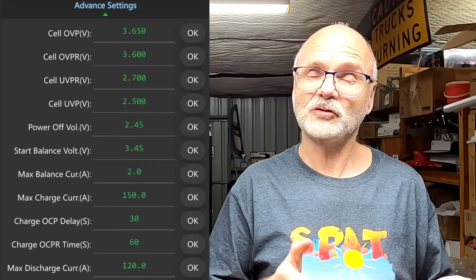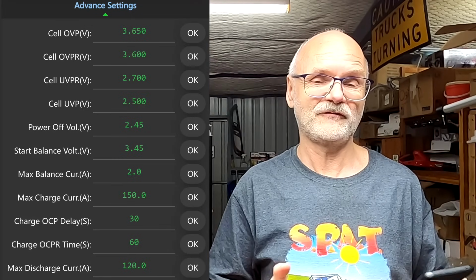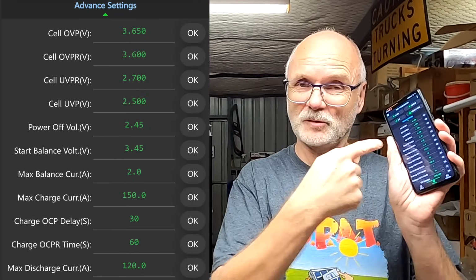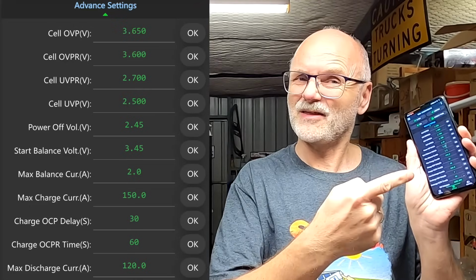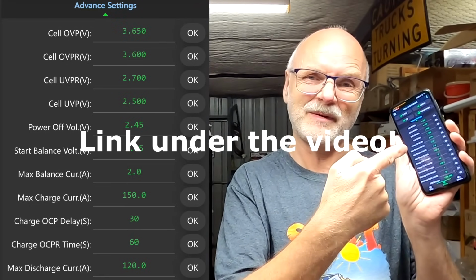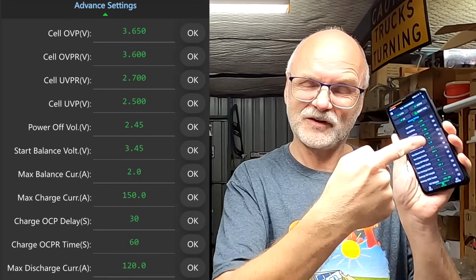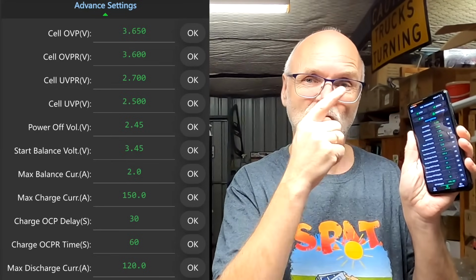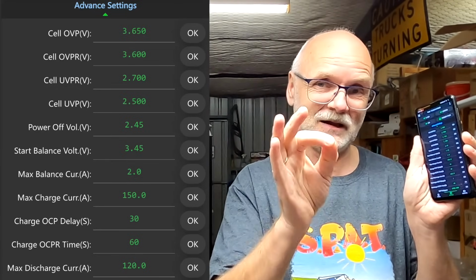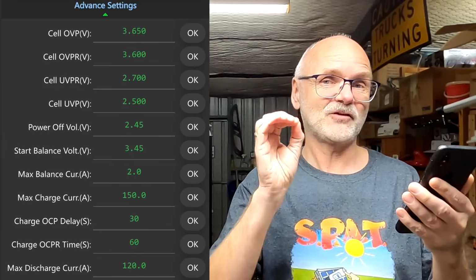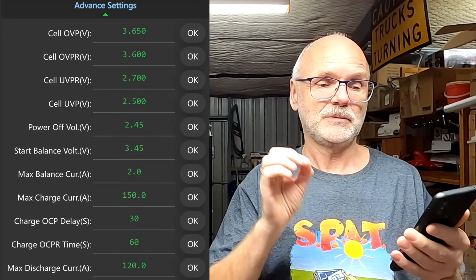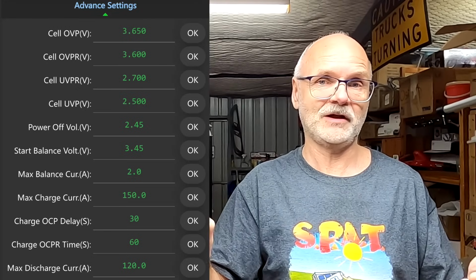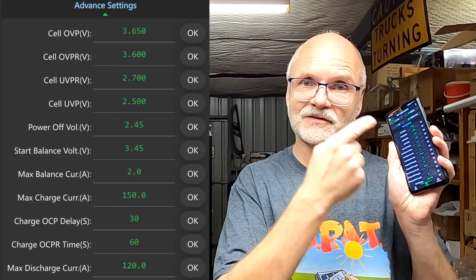And some people still think you don't need a BMS, a solar charge controller is totally fine. No, it's not fine. You always want the BMS. You always want the JK-BMS or any of the other BMSs, but I would recommend the JK-BMS. You always want the BMS for this purpose. This is a safety function of the BMS. It turns off your whole battery if one of the cells, one of the 16 cells here, is over 3.65 volts. Because then something is not right and the battery shuts down. Yeah, it shuts down. Safety reason. BMS is a safety device.